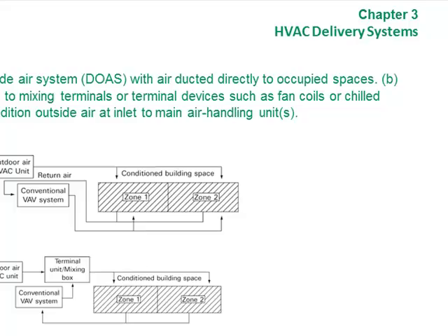But you wouldn't want it in a place like this, I don't think, because we wouldn't want the temperature to drop down to 60 and then go up to 80 and drop back and forth. We want it more even. So you wouldn't use a two-position control when you don't want large variations in temperature, because it's either on or off. A modulating system is better when you want to keep it more on an even keel.